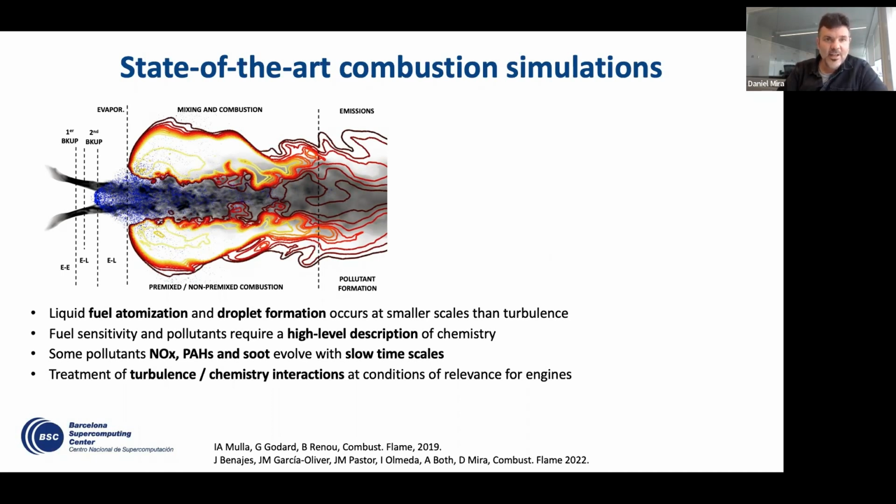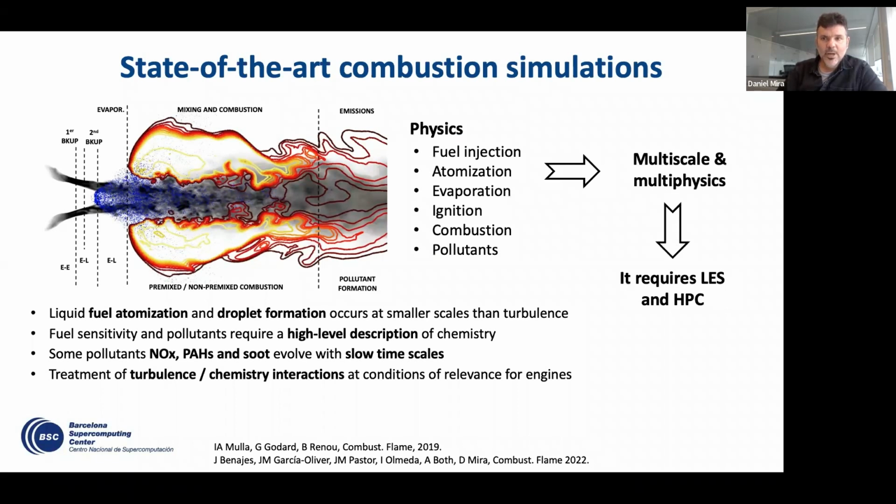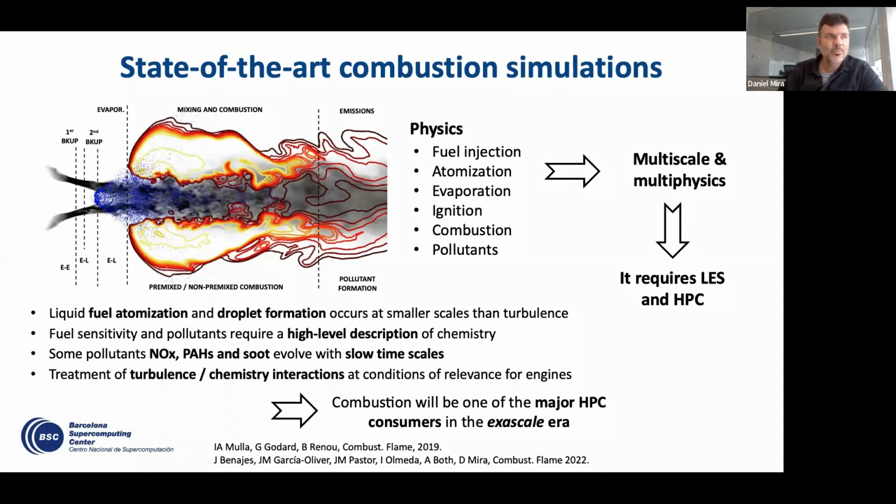Besides, there are the turbulence and chemistry interactions that usually occur at scales smaller than the mesh resolution that we have, which at the end brings a lot of requests for the numerical simulations, because we have to deal with a multi-scale and multi-physics system. And if we are interested in looking at realistic engine conditions, we have to rely on techniques that are high fidelity but not extremely computationally expensive, where LES stands out. And also combined with high performance computing and algorithms. So at the end, with the incoming power of supercomputers coming from the exascale next generation supercomputing architectures, combustion will benefit extremely, and this will bring us the opportunity to address problems that we have not been able to before.